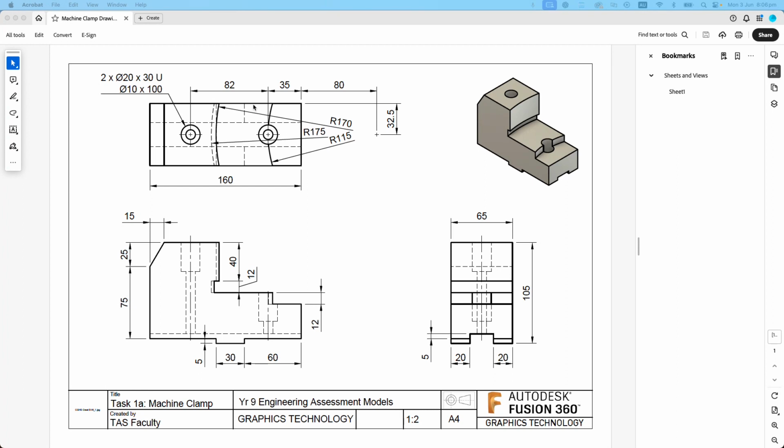So the first thing to note when I look at this is that there are these arcs present in this drawing. And I can see when I look at the pictorial view that this is actually not a flat surface. This is the result of an arc that's cut out, resulting in that curved face there. And I see another curved face here, and I can see the same on the inside. Now, how do I know that is a curved face? Well, I can see there are three radius values here. One pointing to this outside edge, which is basically this one here. Then there's the interior one, which is the undercut there. We've got this cut here, which is there. All right, so mental note, there's something going on there.